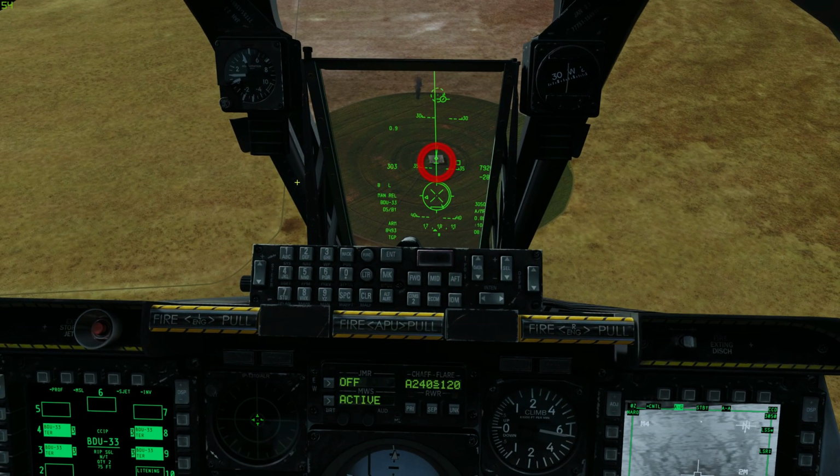We use the desired release cue as the track reference. The DRC represents the desired time of fall, as entered in the DSMS weapon profile. When using a ripple delivery, the DRC indicates the release point with an even number of bombs bracketing the target. The middle bomb will fall at the desired impact point when using an odd number of bombs.